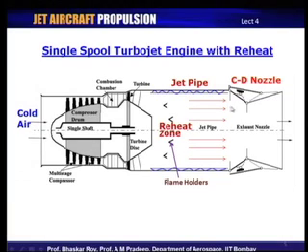So, both ways, if you are going to have a CD nozzle, it is necessary that you have a process by which you can create high pressure and a separate process by which you can create high temperature, so that the CD nozzle can be effectively used to create a high velocity jet without creating a problem of pressure reversal or frozen combustion products in the nozzle face. These are some of the fundamental issues that a jet engine designer would have to contend with at the time of creating this jet engine.